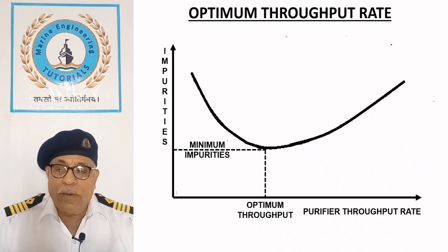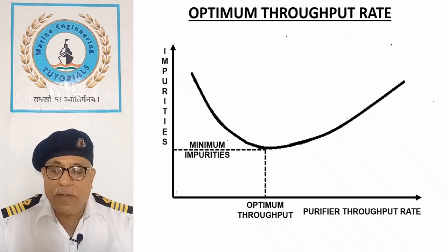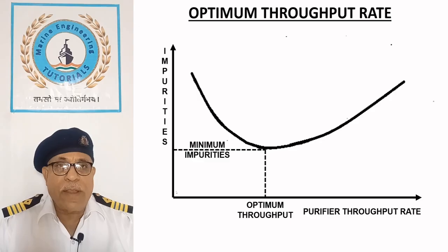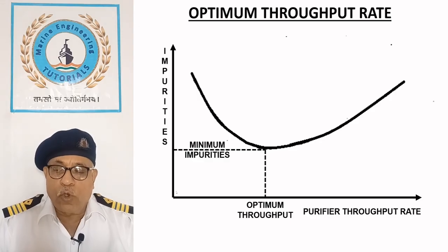Under normal operation, it is recommended that after shutting down the main engine, the purifier should be kept running for 12 hours to minimize corrosion caused by acid vapors condensing as the engine cools down.